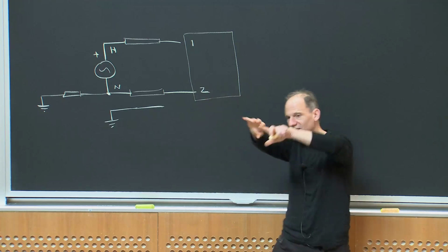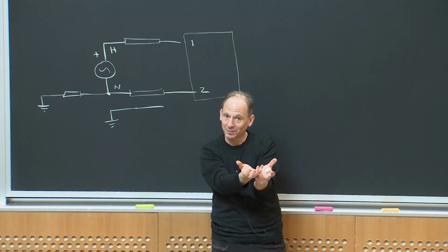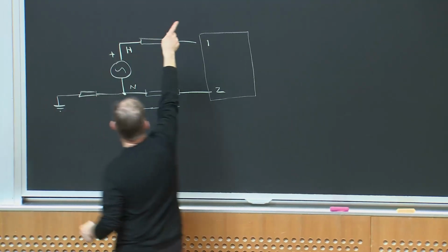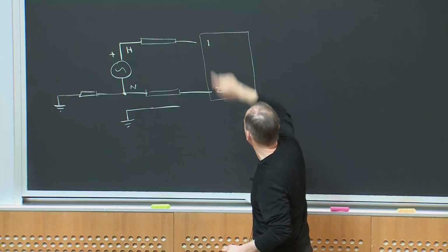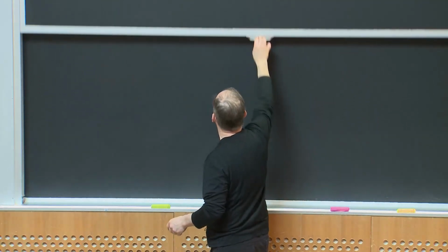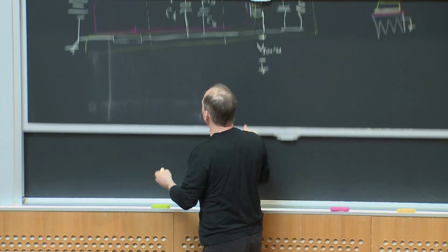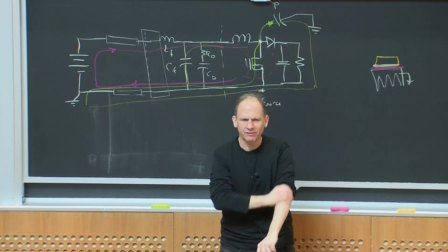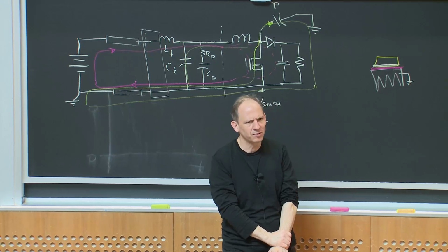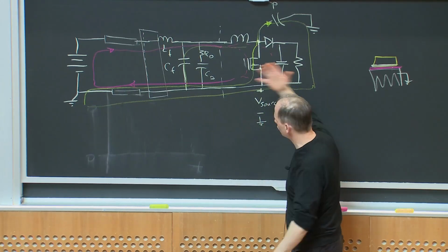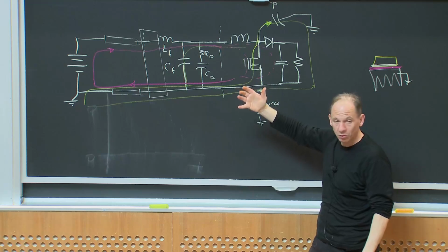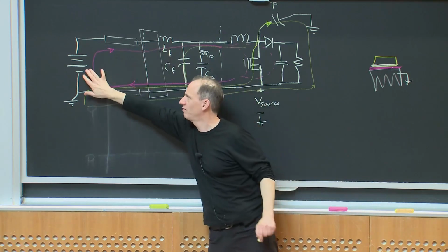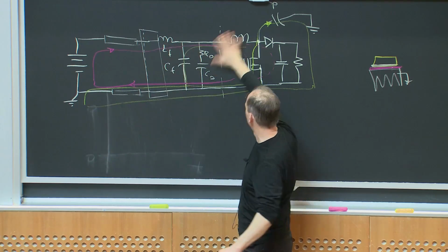Okay? And since the case happens to surround whatever the device is, like the power supply, it could be, in fact, if I had a boost PFC circuit, it looks exactly like the structure I just drew, except that instead of being powered by DC, it's powered by AC, and I essentially insert a rectifier here, right? That's what a boost rectifier looks like, right? The front end of a lot of power supplies. So, you know, this structure can very much represent what would happen in the AC case too, except that somewhere I put usually a full bridge to rectify an AC voltage, which I'd have over here, to DC